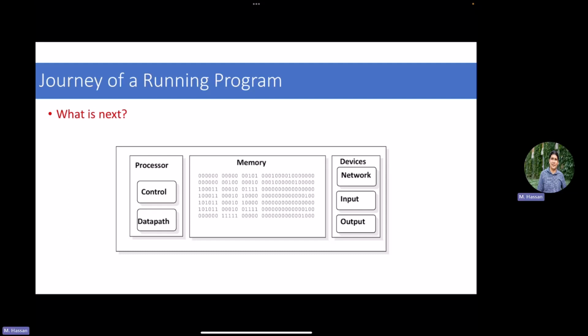So why is it very problematic for variable width instructions to execute? This is one problem with CISC hardware, that some instructions are variable width, and then the program counter needs to do complex math to jump to the next one. But if all the time you have a fixed width instruction, 32 bits all the time, for example, then I know once I finish executing this one, I add 4, which is basically bytes, which is one word, to jump to the next one, right? So that's a good thing.